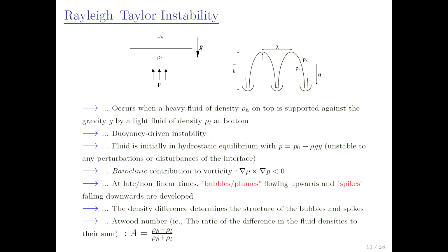I set the simulation from a steady state. Yes, highly compressible fluid, but this is the trick here. I set this pressure like this, and then I let them flow and evolve. So it's not a constant density here, just the initial density value, 1.2 as the low density, and depending on the Atwood number. Then it will not be Rayleigh-Taylor instability. You get a transition flow, because you start from a steady state solution. You need to start from steady state and then put a perturbation on top of that. Rho g y is not steady state.